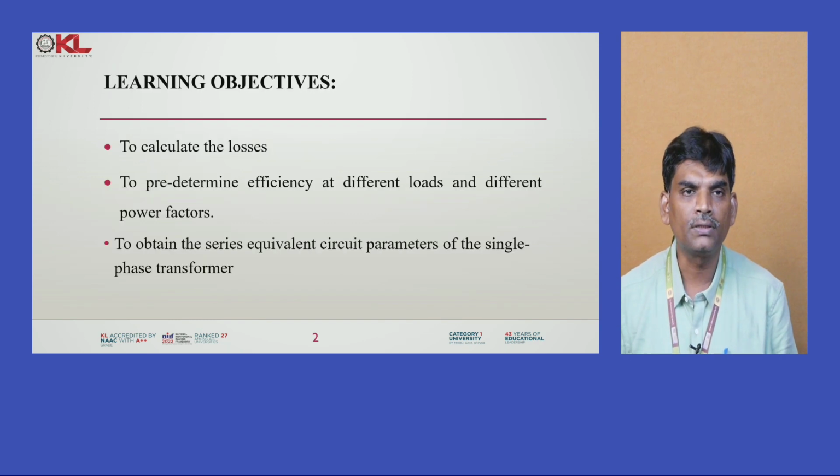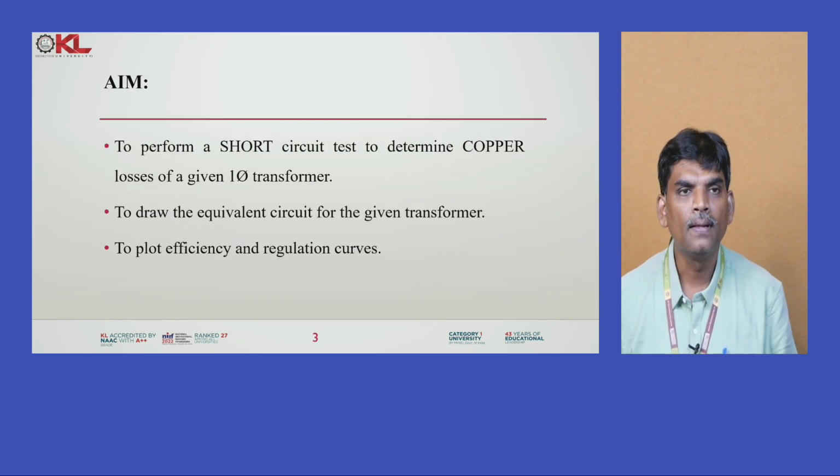These are the learning objectives: to calculate the losses and predetermine efficiency at different loads and different power factors, and to obtain the series equivalent circuit parameters of the single phase transformer. So, the main aim of the short circuit test is to determine the copper loss of a given transformer, draw the equivalent circuit of the transformer, and plot the efficiency and regulation curves.